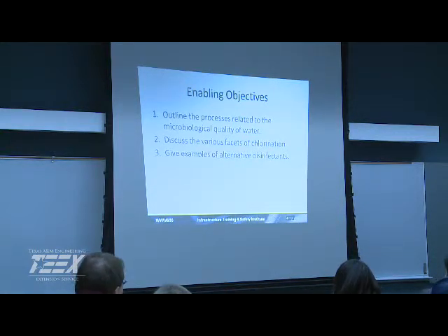And then we're going to look at some of the alternative disinfectants. I know here we've talked about there's not a lot of things going on with chlorine dioxide or people using chloramines. State of Texas, if you're running a surface water treatment plant, you're going to run chloramines, and that's just a requirement. So everybody's doing that.